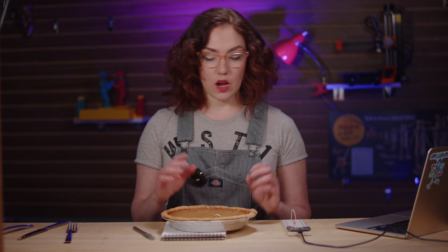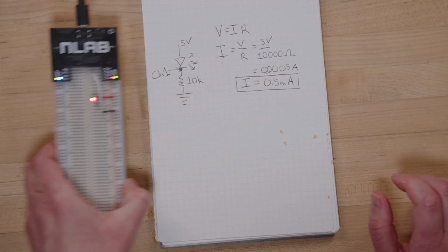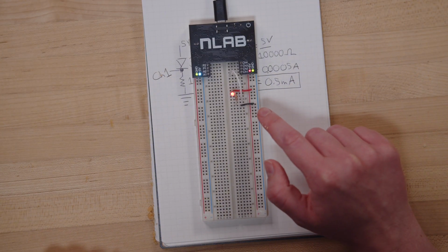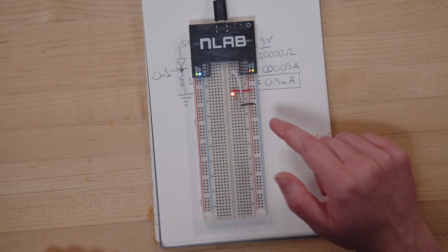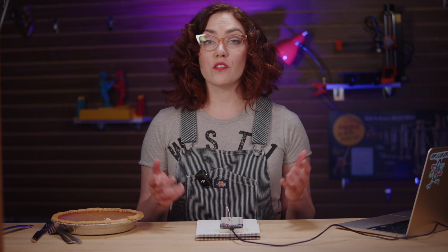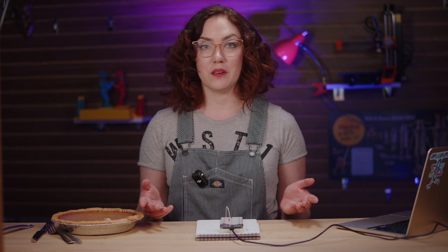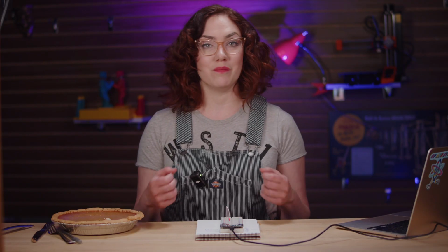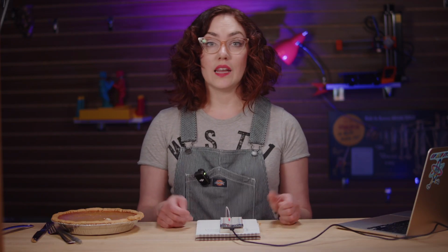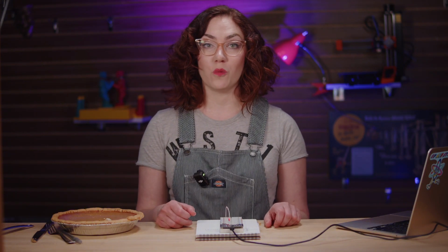Yes. Okay, focus. So that means something on our breadboard is using 2 volts. I'm putting my money on the LED because it's doing something. It's lighting up. If there's something in your circuit that's doing something, chances are it's using voltage because it requires energy to make a beeping sound or read your heartbeat, whatever it's doing. And that checks out because in general, LEDs do require about 2 volts to work.